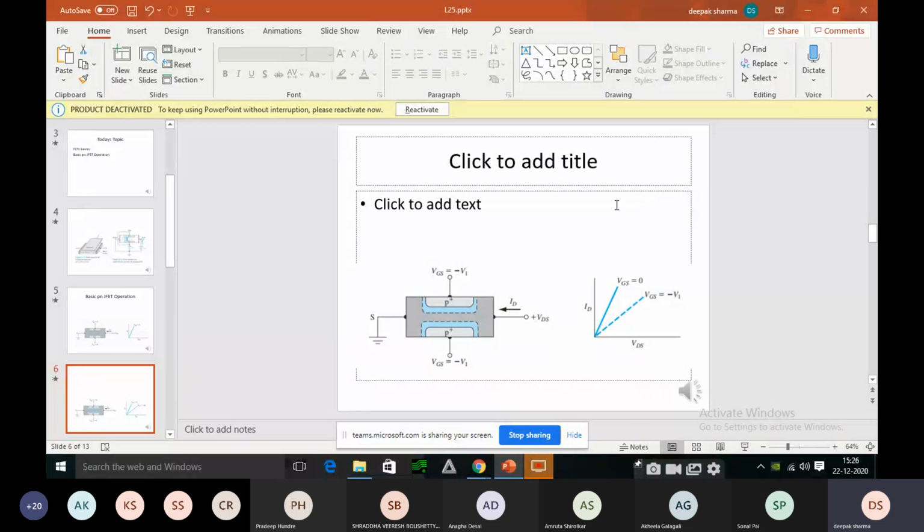Yeah, so what I was explaining here, I was saying about the current, right? The current is decreased. Why? Because there is less space for charge carriers to move. Why is there less space? Because of increased depletion width. Why increased depletion width? Because of reverse biasing. Why reverse biasing? Because negative potential is applied here. That is very clear, right?